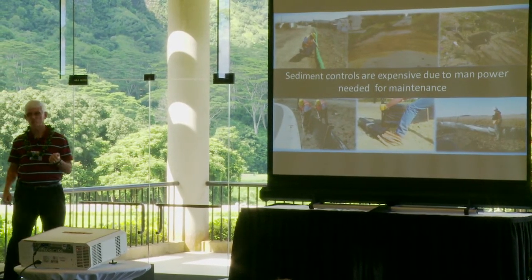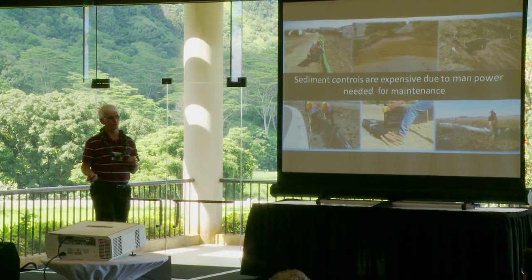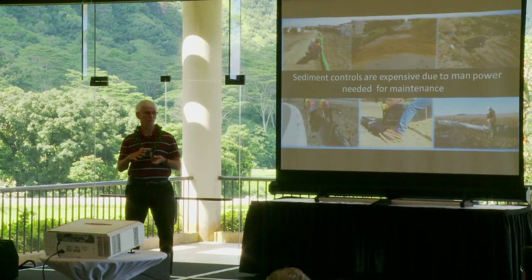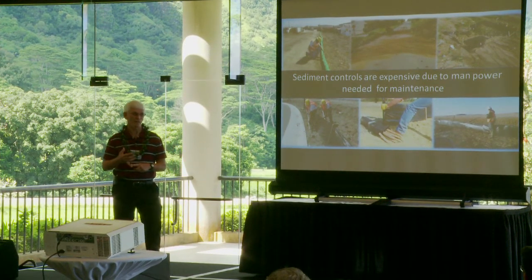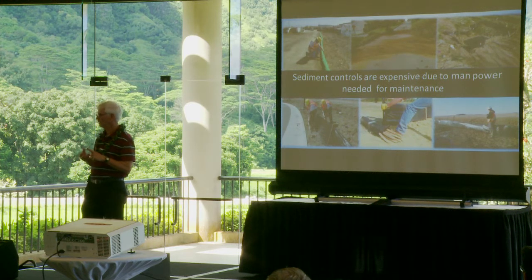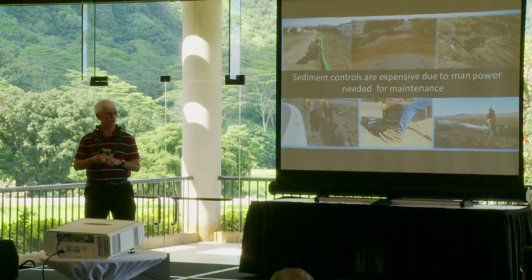So, before we start, I'm going to go ahead and say this. Any kind of class always talks about erosion control and sediment control. Erosion control is anything we put down on top of the bare soil to keep raindrops from hitting it. It's our final cover of vegetation, grass, turf grass, rock, the pavement itself. That's erosion control. You're usually one and done.